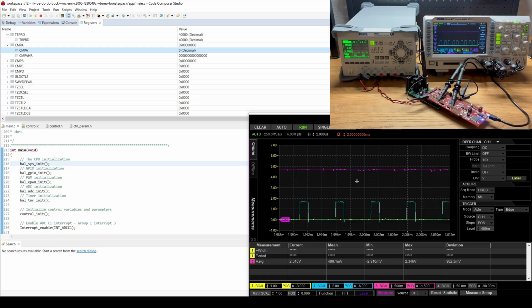Of course, many other issues can also prevent an interrupt from executing correctly, such as incorrect interrupt configuration, peripheral settings, or software bugs. But as we have seen in this demonstration, CPU load is certainly one of the first things worth checking. CPU load doesn't usually fail gradually, it often fails suddenly when the processor can no longer meet its real-time deadlines.